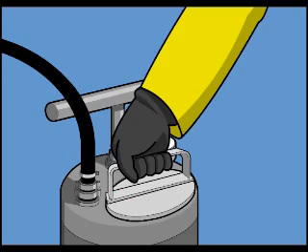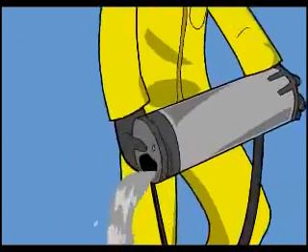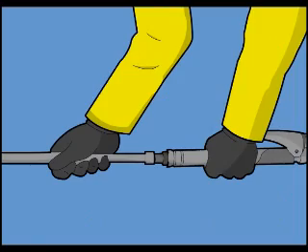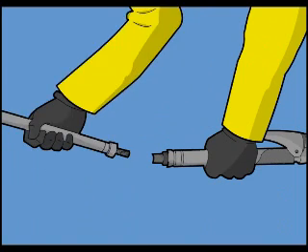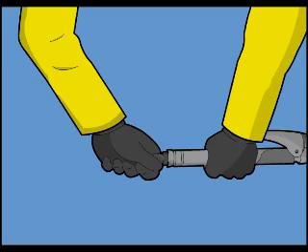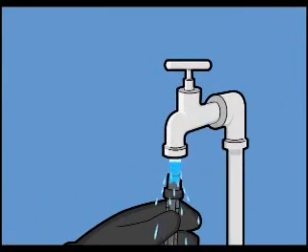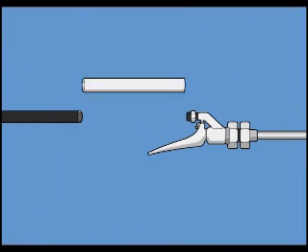Depressurize the tank and pour out any remaining liquid into a container, as it can be used for spraying during the next day. To clean the strainer inside the trigger valve, disconnect the trigger valve from the hose and unscrew the trigger on-off valve handle. The strainer can then be washed. Reassemble the trigger valve with the clean strainer.